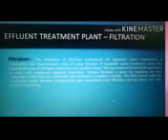Tertiary filtration is aimed at removing the fine suspended solids that are carried over in the secondary clarifier. The BOD associated with the suspended solids also gets removed during filtration, resulting in low SS and BOD effluent.